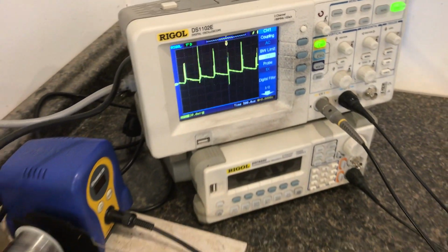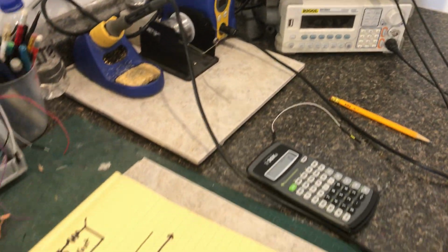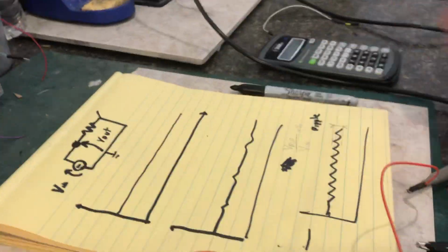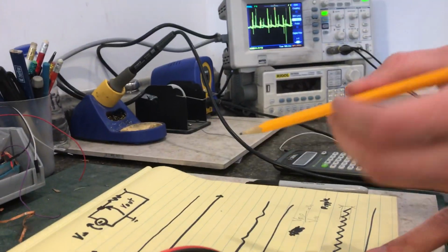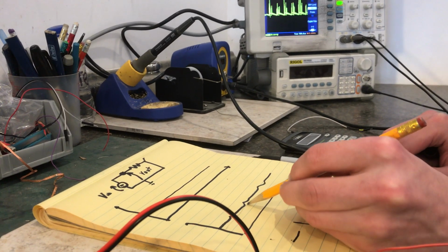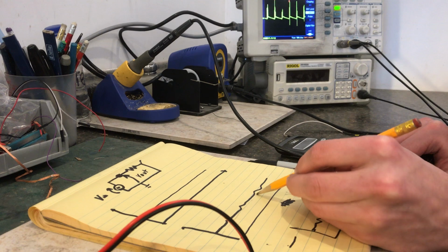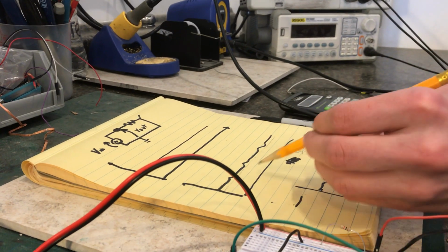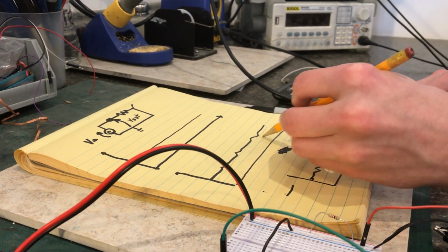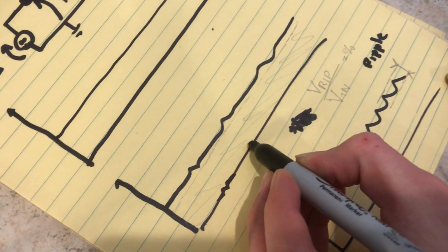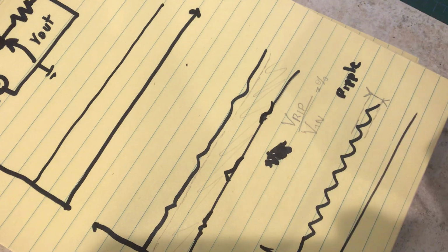So real quick back here, explaining DC and AC coupling. Whenever you do AC coupling, it takes every bit of voltage that doesn't change, and that would be everything from the lowest peak down to ground, and gets rid of it. And so for this one you would just see that. All right, that's the idea.